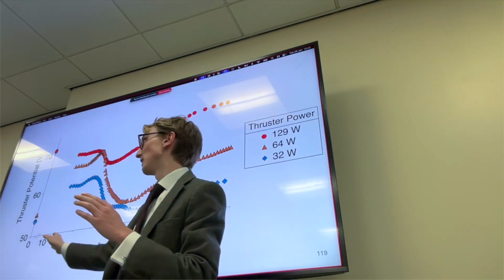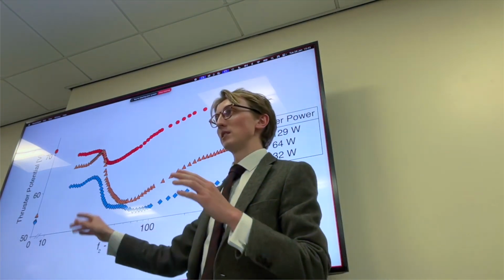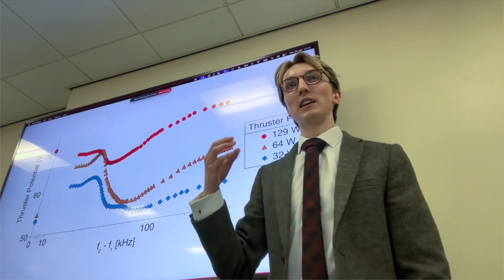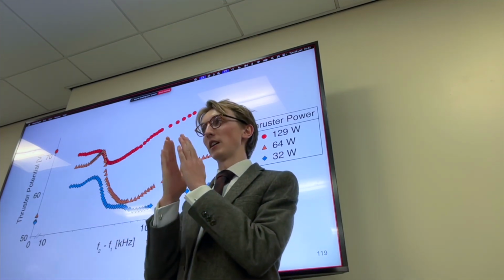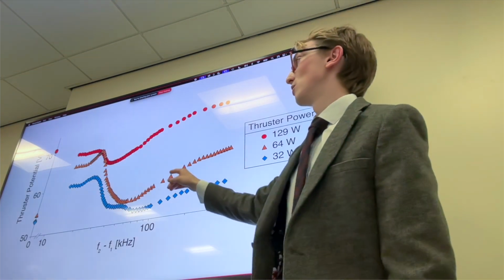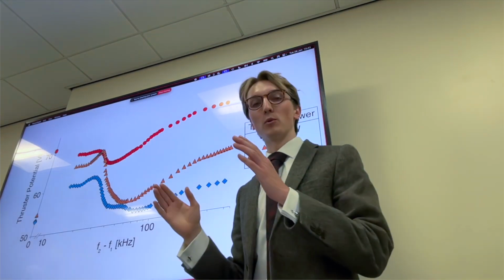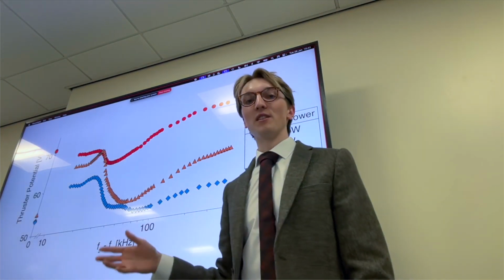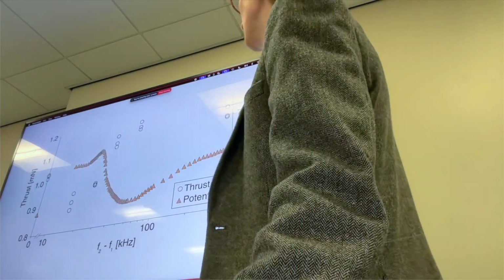Here on the left side of the diagram, they're quite close together, and on the far side, we have a high frequency separation, so they're further apart. Of note, the microwave frequencies are in the gigahertz range, and this frequency separation is in the kilohertz range. So these are really close together microwave frequencies. You can see here that the thruster potential has quite a strong dependence on the frequency difference of these 2 microwaves. So this is a good indicator that thruster performance might also be affected by the frequency difference of the microwaves. So this is what I investigated next.